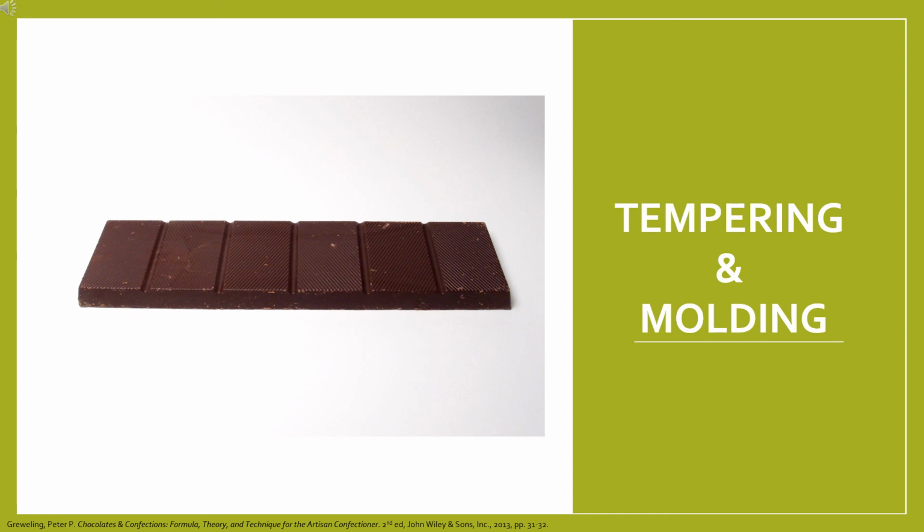Before the chocolate manufacturing process is complete, the chocolate must be tempered. Tempering is done to create the characteristic snap upon setting and shiny appearance. It is achieved through the continuous agitation of chocolate at a controlled temperature while being seeded with stage 5 cocoa butter crystals. After the chocolate is properly tempered, it is deposited in the desired molds and cooled in a manner that ensures proper crystallization and reduces the chances of sugar bloom.